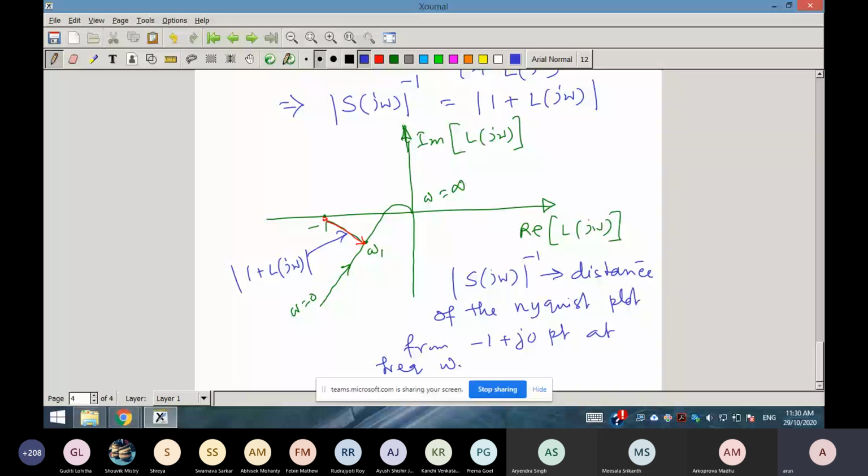As you know, the -1 point is a critical point for stability of the system. If there are any parameter variations or unmodeled dynamics, the Nyquist plot may touch it. You verify that your nominal plot is not touching the -1 point, but because of some parameter variation, the Nyquist plot of the loop transfer function may touch the -1 point.